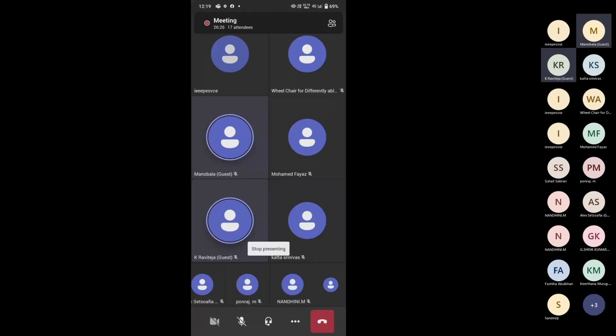Are you using a CNC milling machine or a CNC to draw this diagram alone? We can use it as a milling machine also, sir. We can give a G code and it will draw whatever we want. For the demo, we are just drawing PCB Gerber files. We design in the EasyEDA website, download it as a PCB, convert it into a PDF, and after that it goes into G code and it will draw like this.